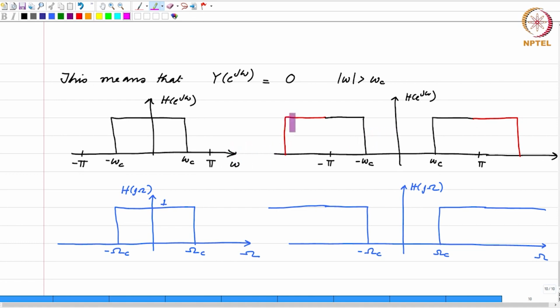If you drew this, you will see that these are the responses corresponding to the frequency response that occurs at minus 2 pi. Similarly, this is the arm of the response that happens at omega equal to 2 pi. Therefore, this is the highest frequency in the discrete time case, whereas in continuous time case omega equal to infinity will be the highest frequency, alright. So, notice carefully the differences between these two cases.